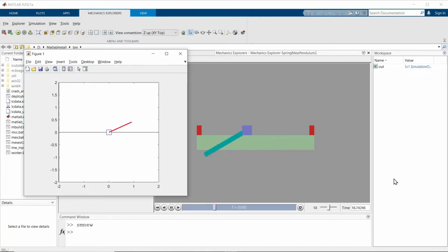This one is on how to model a collar that is sandwiched between two springs on either side, and it has a pendulum coming down from it. The Matlab model is the one on the left here. I did it through deriving Lagrangian equations of motion and then simulating through ODE45 and animating.